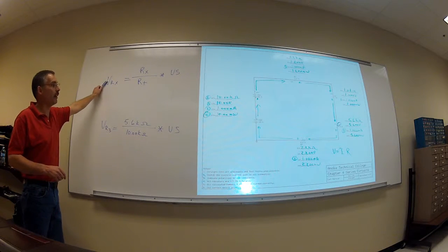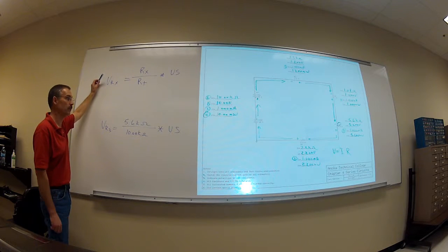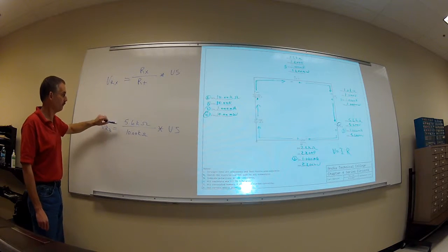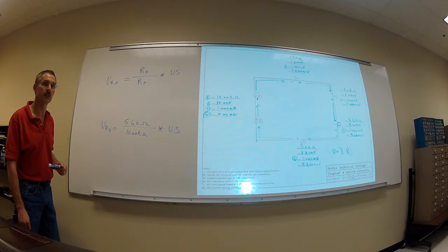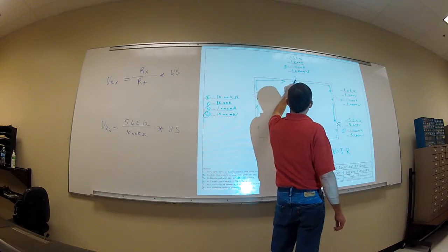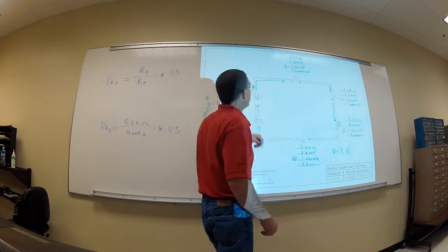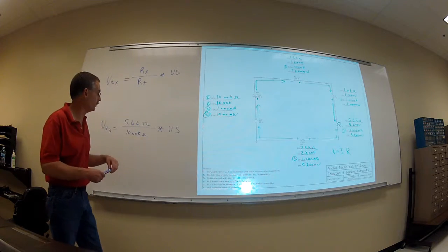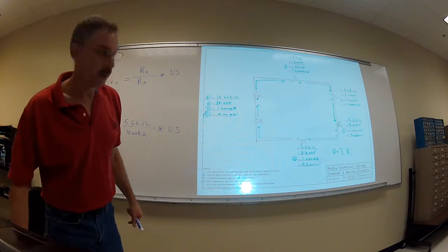So make sure you have that written down somewhere. This is one that we use. You'll use it through the whole life of this program. Did you end up with 5.6 volts? Yep, you should. And so we can do that with any given resistor. If we only want to know what the value of this one resistor is, we can just use that voltage divider formula and get our voltage for that. And we're going to use that formula here for our next one.